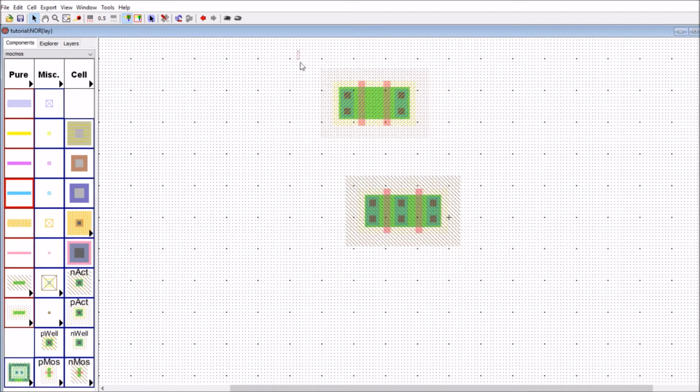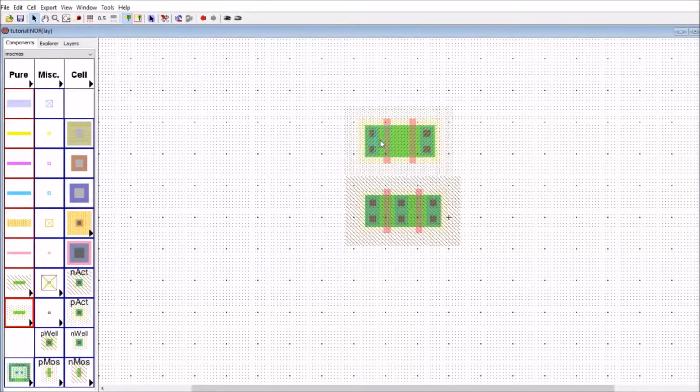So this is the two PMOS devices now sitting in series. So we can butt these together. That's the wells, the N well and the P well butted together. So again, on this side here with the PMOS devices, it would be the source to the drain, and yes, again, this would be the drain as well. So source to the drain, to the drain, to the source.